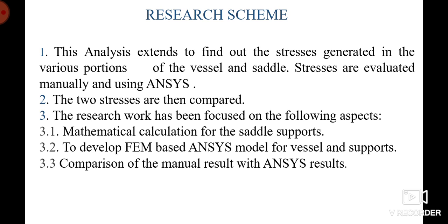And using mathematical formulation and considering horizontal pressure vessel as a simply supported beam, stresses acting at various points will be calculated, and using ANSYS software, stresses at various points will also be calculated. So both of these values will be compared thereafter, and after comparing these two values, we will be able to reach a conclusion that which method is most suitable for the designing of the horizontal pressure vessel. Either it is ANSYS software analysis, or it is simply mathematical formulation.